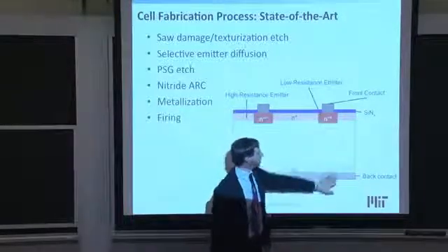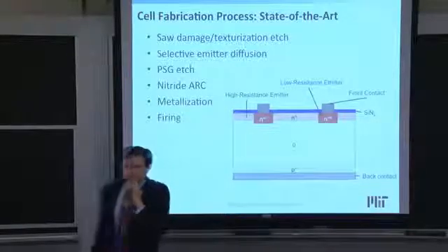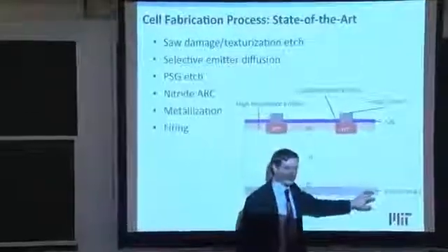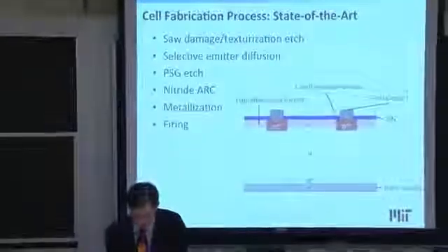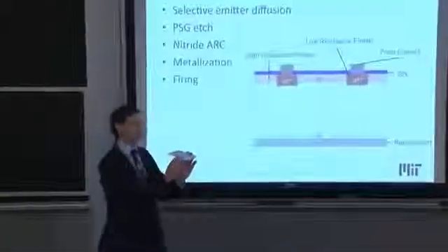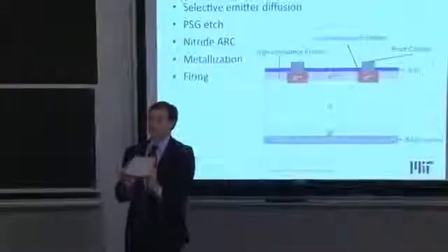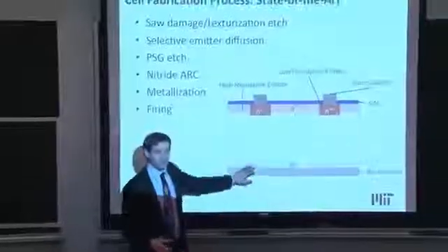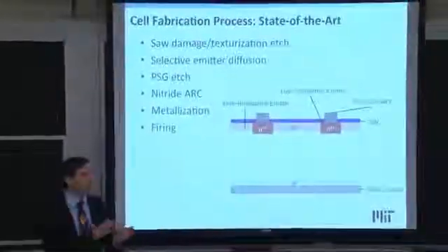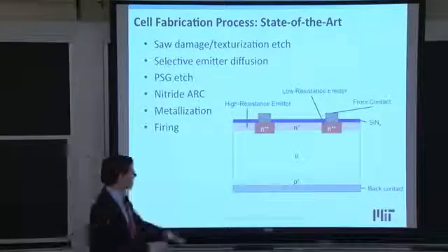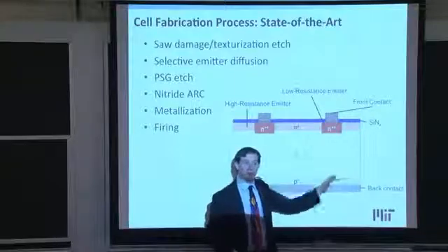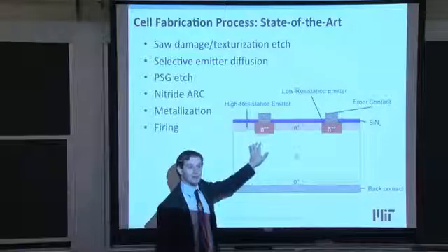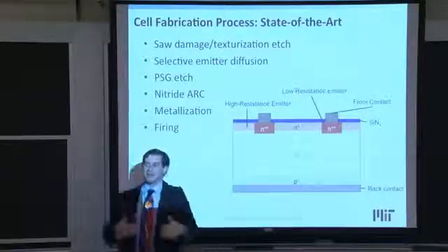And so for each of these different processing steps, somebody had to sit there and think deeply about optimization of different functions. The aluminum on the backside, somebody had to think about, gee, how do I prevent the wafer from bowing too much due to coefficient of thermal expansion mismatch between the aluminum and the silicon? Somebody had to think about, how do I create the right eutectic with the silicon? The aluminum silicon eutectic is around 577 degrees Celsius, so that you create a good ohmic contact in the backside. How do I diffuse in a certain amount of the aluminum to create this back surface field to prevent back surface recombination? How do I get the right back surface reflectance of the light coming off of here so that I have multiple optical bounces through my device? And so forth.